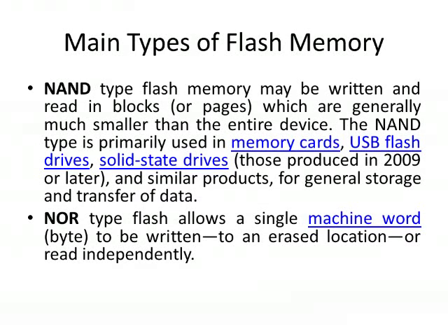NOR flash memory supports 1-byte random access, which allows machine instructions to be retrieved and run directly from the chip, in the same way that a traditional computer will retrieve instructions directly from main memory. NOR flash has an SRAM interface that includes enough address pins to map the entire chip, enabling access to every byte stored within it.